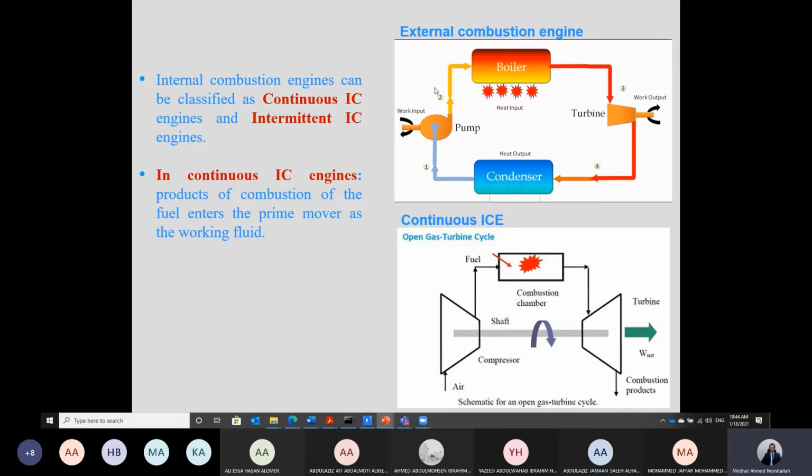So in this case, the steam turbine will be providing the basic load, and we can run additional gas turbines to provide the additional required electrical power. A gas turbine is easy to start. In a minute, you can just start a gas turbine, but a steam turbine, Shabab, it takes about 2 to 3 days to start.